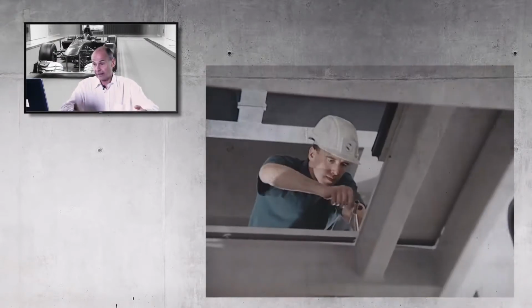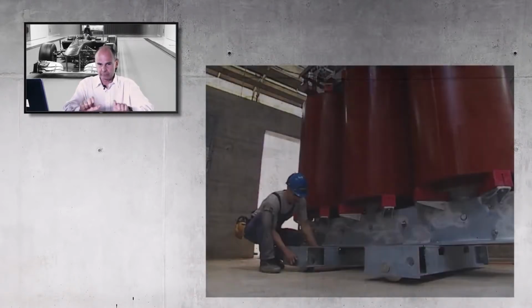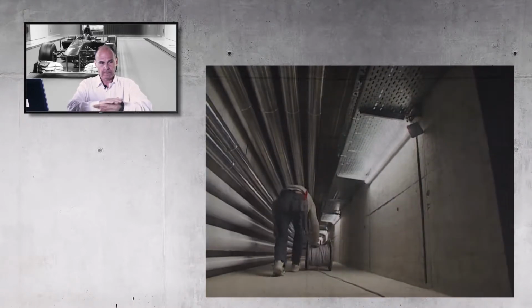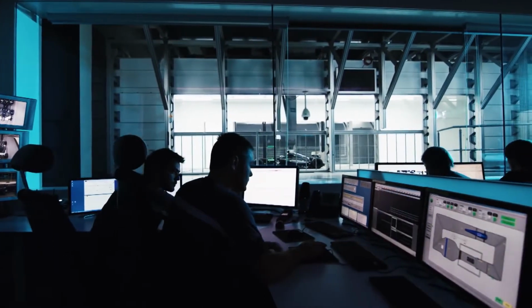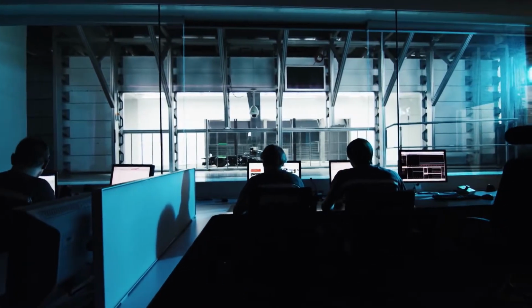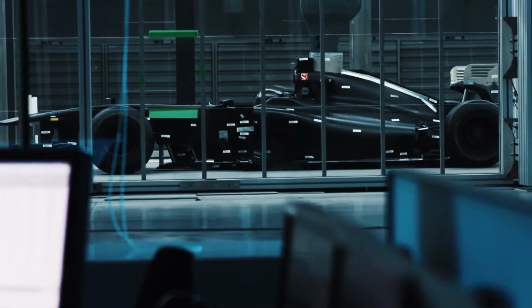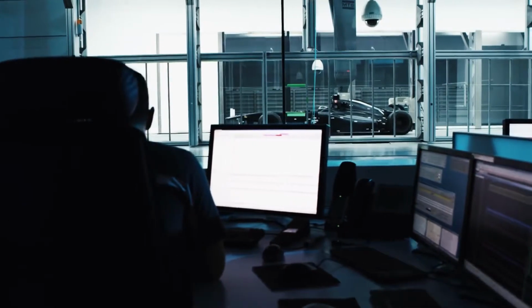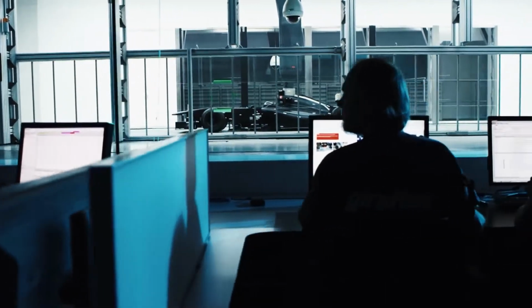And this technology has then been evolved and developed and matured. So we now have a moving ground system that is so well engineered that we can put a race car on top. We can take the weight of the car and the aerodynamic downforce of the car, which is much greater than the weight of the car, it's getting into tons, and do aerodynamic testing on our race car up to 80 meters a second, physically possible, not allowed in the rules anymore, used to be, but physically possible, and we have no problem whatsoever with the moving ground system, which with a synthetic belt was an impossible dream, or close to an impossible dream.